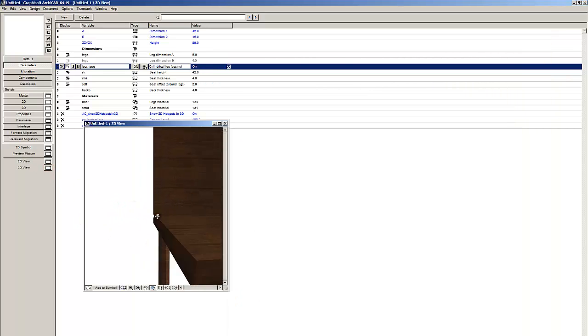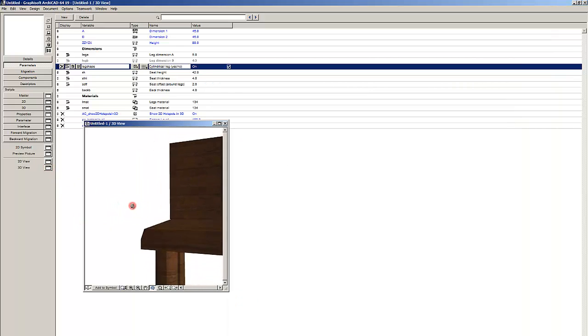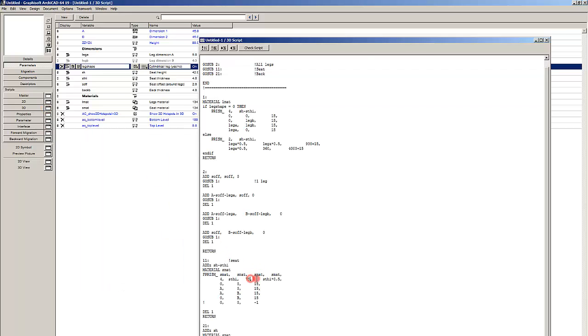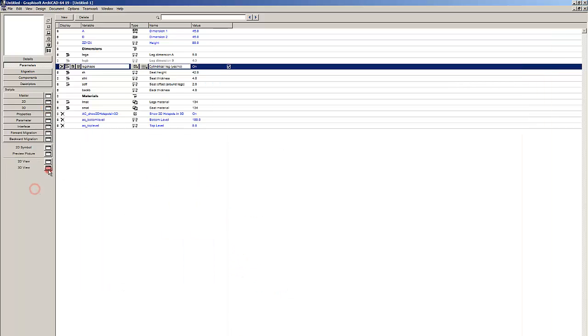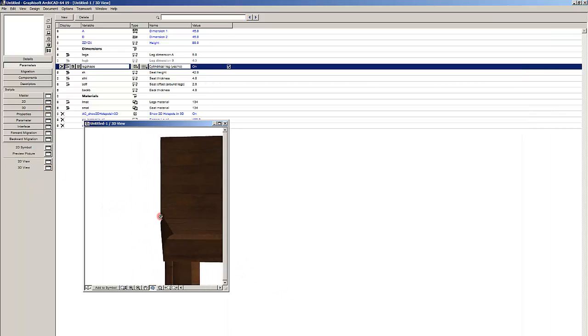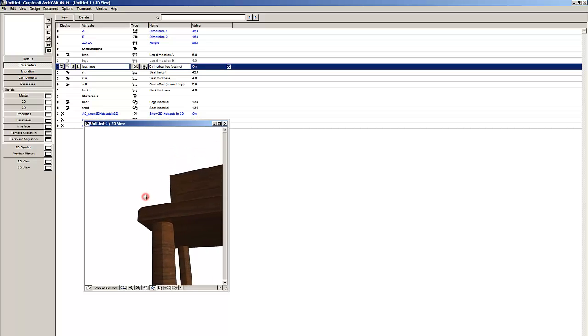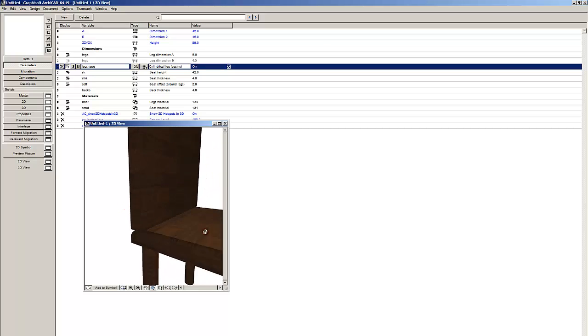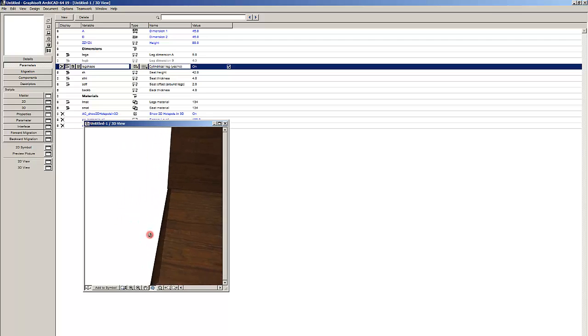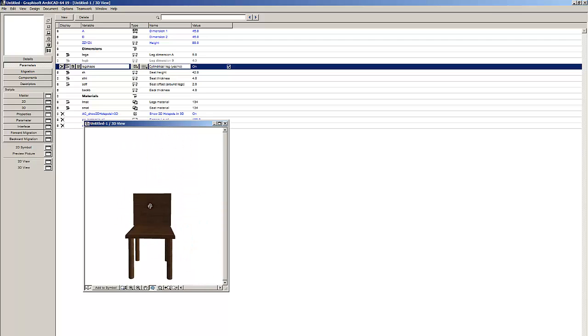And it changes its angle, of course. If you want it to be filleted, you will have to use the angle of 0 degrees. And it's a perfect fillet. And it's very useful because it's the simplest way to do it. You just created a very complex 3D object by just using a simple prism command.